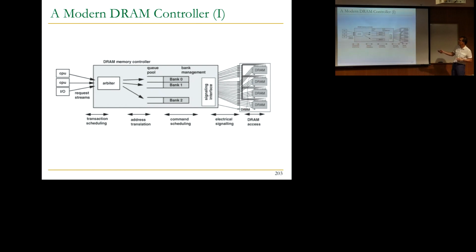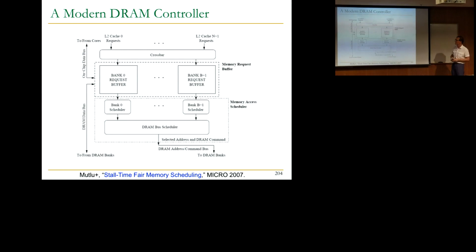So if you want to have a memory controller that can attach to many different types of DRAM, you need to replicate this, right? Which may not be that easy, as you can see. And this actually consumes a lot of the chip area. And then there's, of course, the RTL part of the controller, which is more logic part that does the arbitration and the bank management.